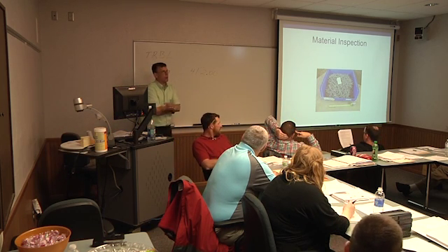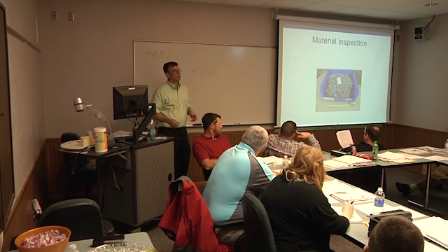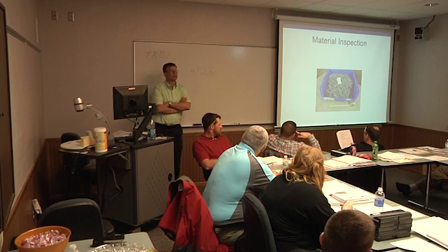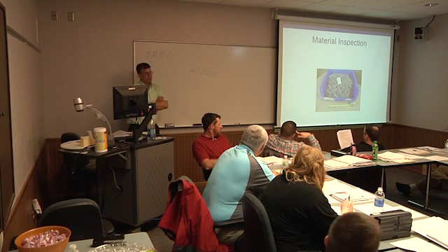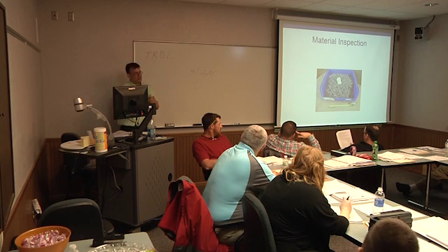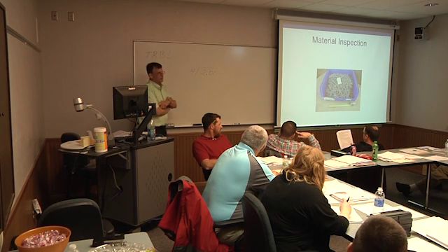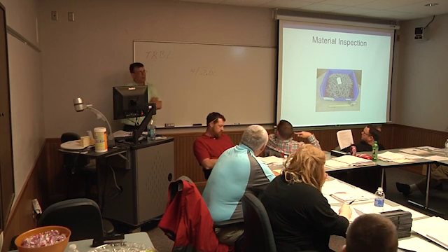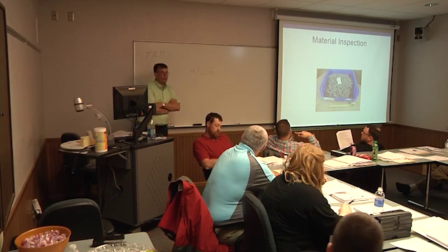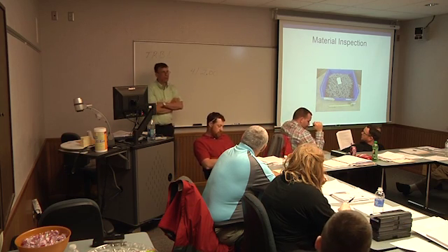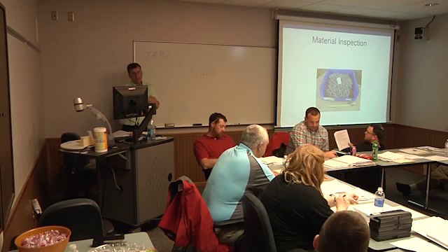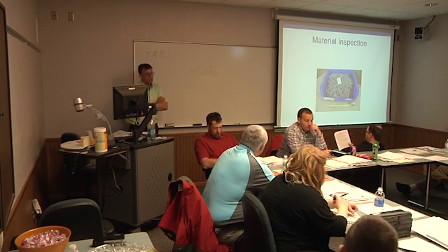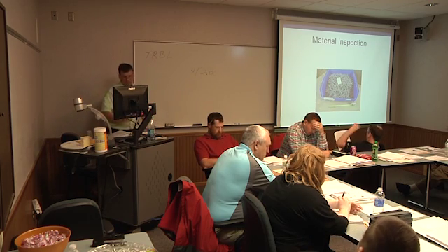Little trick question I ask students. Let's just say you're producing small products, little screws, or in this case, you're a nail production company. Do you inspect every one of those things when you're producing? More times than not, students say yes. You visually inspect every nail that you produce, every little screw. Now, some products are big enough that yes, it is practical and beneficial to inspect. If you're producing automobiles or something along that line, yes, inspect every one of them. But for something like this, you do sampling. Every so often you draw a sample, you randomly measure to make sure that they are meeting the specifications.